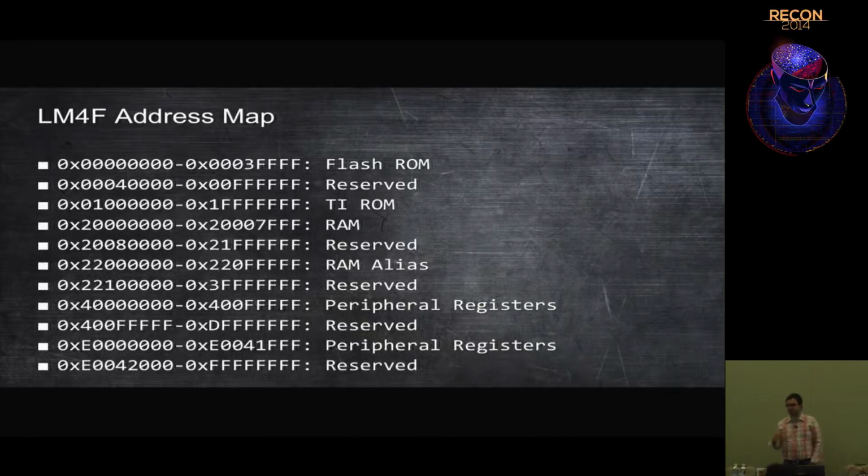So that's where you can access USB, PCI, LPC, the AD controllers, the fan controllers, and the GPIO controllers, everything else that's plugged into the chip. And your code can actually either access these registers or you can use the library that TI provides. In Apple's case, they seem to do a little bit of both. So some code directly talks to peripheral registers, and then you have to use a data sheet to find out what register is what. Other code uses the API library, and then it's a lot easier. So you can just read what the API call actually is.